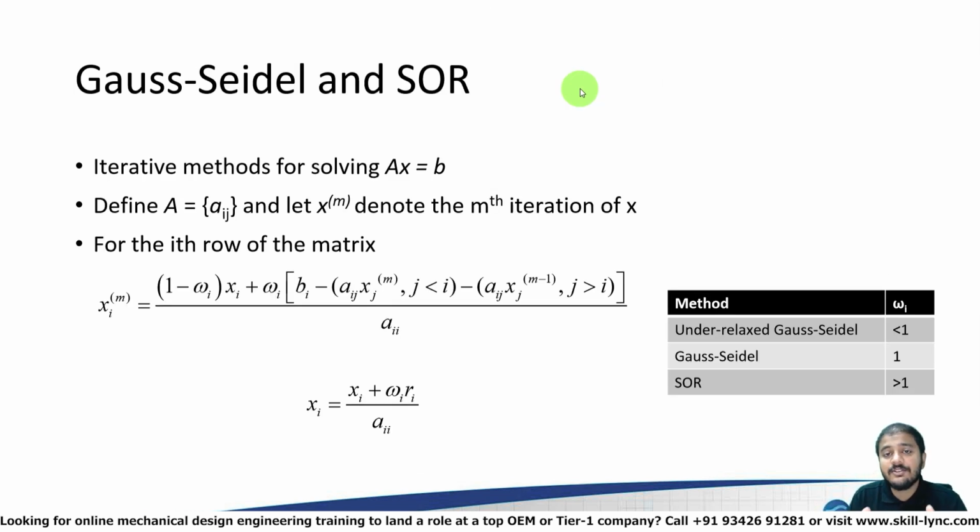Now, how does Converge solve the linear equations? Well, it uses some pretty standard algorithms. We use Gauss-Seidel SOR. Now remember, all these methods can be over-relaxed or under-relaxed. An iterative method is basically for solving a linear system Ax equal to b. The idea here is that x is what you're solving for, correct?